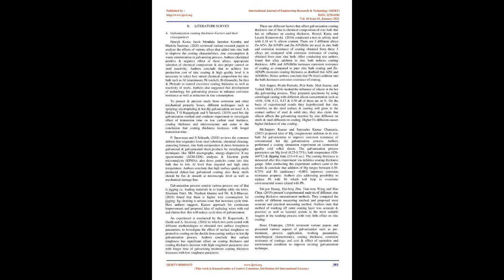appropriate selection of chemical composition and also proper control of steel reactivity. The authors conclude that to achieve low production cost of zinc coating and a high quality level, it is necessary to select the best suited chemical composition for the zinc bath, such as aluminum, Ni (nickel), Bi (bismuth), Sn (tin), and Pb (lead), to control excessive coating thickness as well as reactivity of steels.